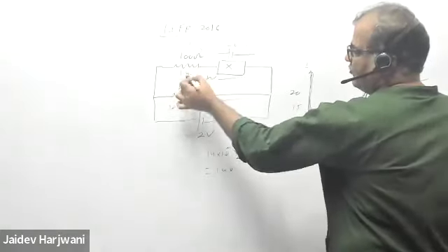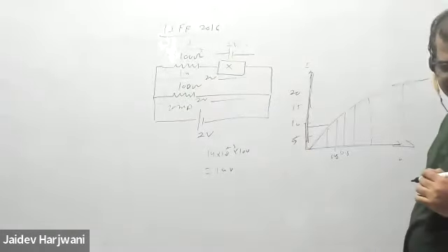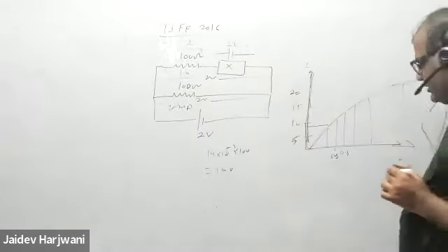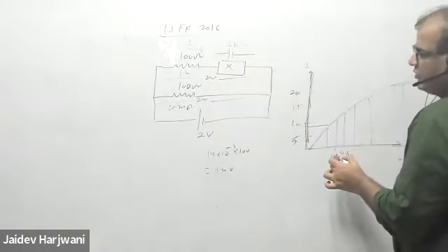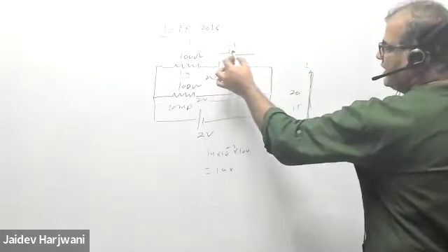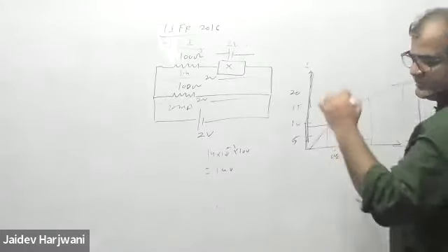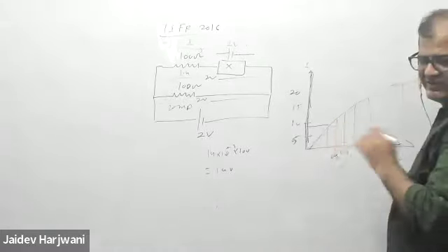So 1.4 volt and 1 volt here, 2.4 volt cannot be there. Are you getting the point? You cannot have 0.5 volt, because 0.5 volt will give you the current 9 milliampere and 0.9 volt. If you go to 1 volt, this becomes greater. So somewhere the value is between these two.